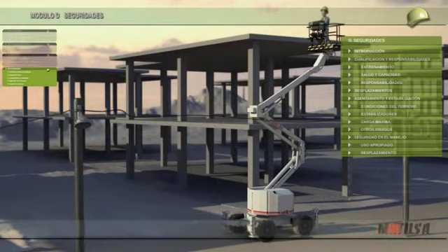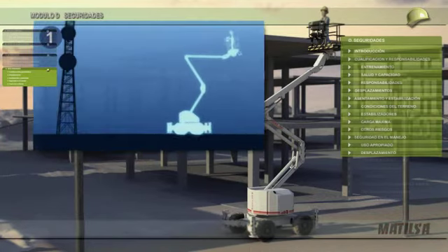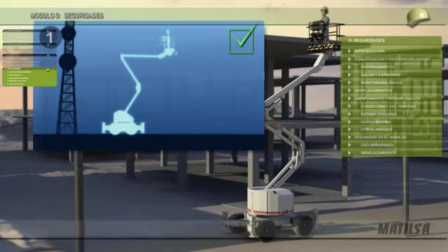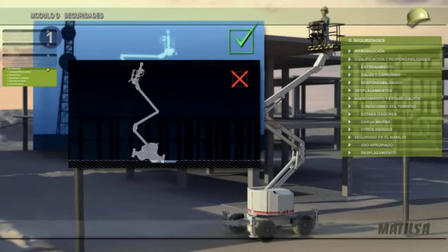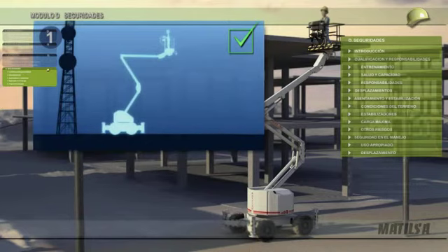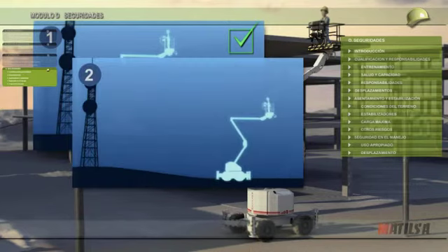We will only be able to transport with machines which are designed to do so. These are the so-called self-propelled platforms, which may do the transporting even in the up position. The transport of the platform will only be possible when the ground is steady and completely level. Uneven parts cause lack of stability when the machine is up and may cause involuntary falls of the worker onto the ground. Do not use the platform on slopes or hills.